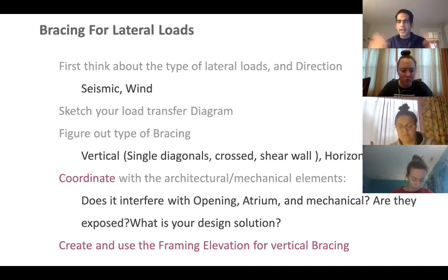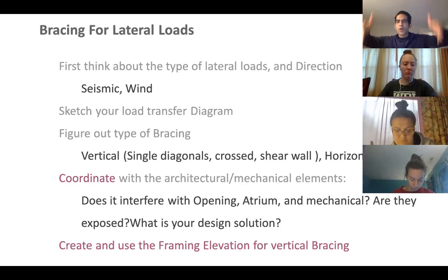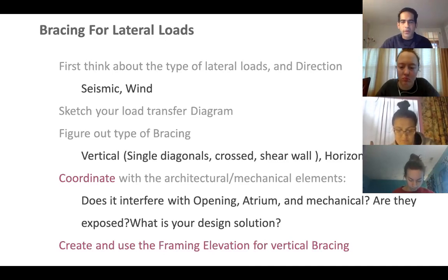What's going to happen is that on that specific span, I cannot put the window in the middle, right? Because there is a brace coming, crossing. So these are the types of things that you have to think about. One of the good places to bring lateral stability to your building is wherever you have the staircase, because the 3 or 4 sides of the staircase can be easily reinforced all the way through all levels. So that's one good place for the bracing.